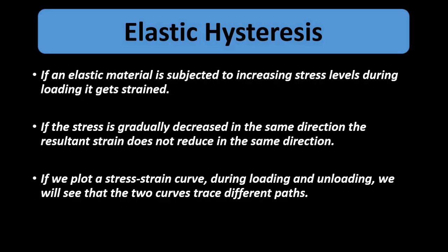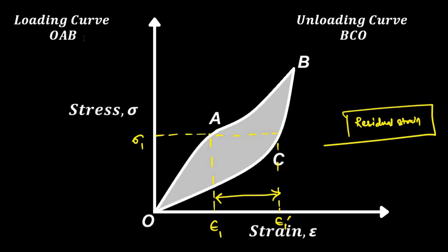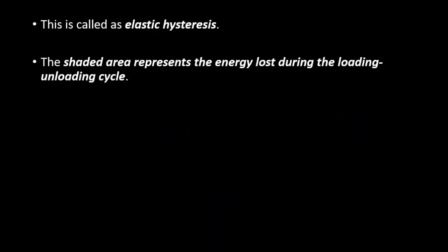So here we have discussed the three main important concepts. Elastic after effect, which is the delay of the elastic material to return back to the original shape and size. Elastic fatigue, which is the breaking or snapping of the material due to continuous repetitive application of stress in alternate opposite directions and the resulting strain. And elastic hysteresis, which is the residual strain left in the elastic material during the loading and unloading cycle. Loading is basically increasing stress gradually, and unloading is decreasing stress gradually. So this is the thing.